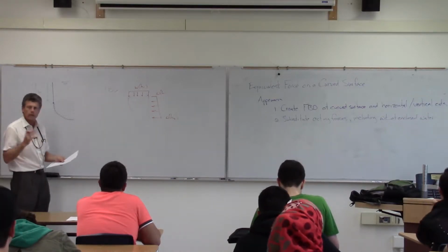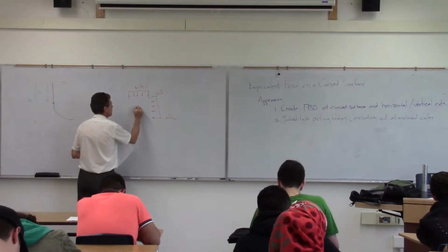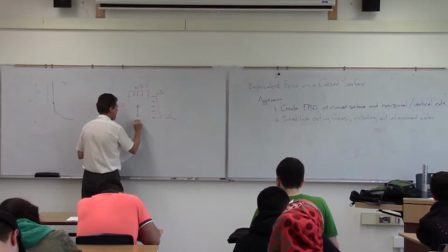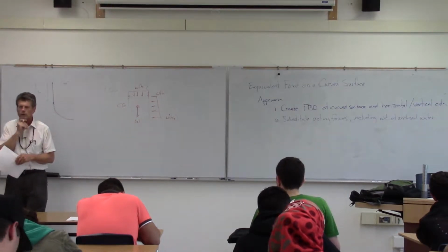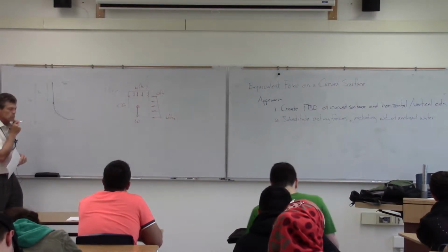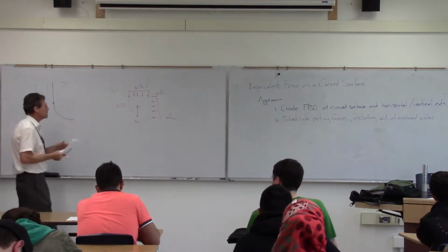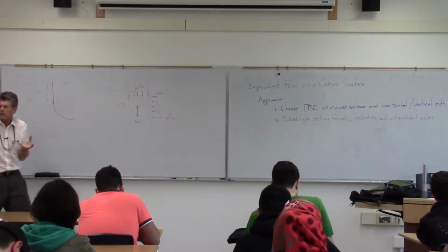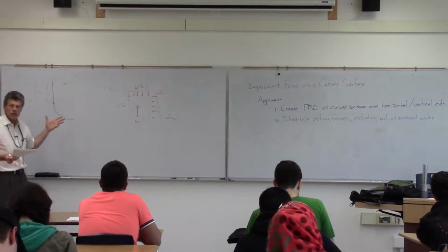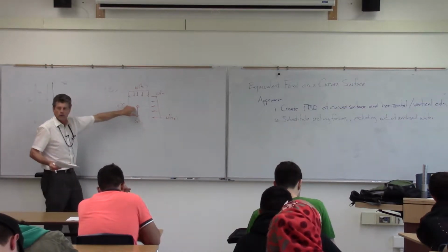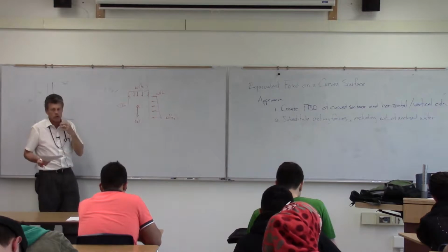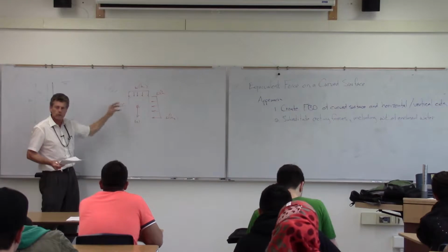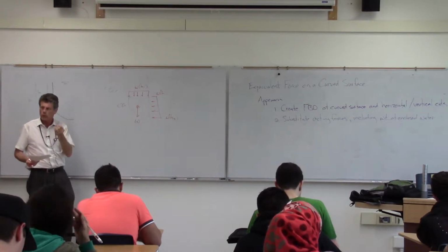The final piece then is we have to find the CG and include the weight of that enclosed volume. So that's something we can do, hopefully, if the curve is something that's nicely defined, like a parabola or a circle or something like that, we can basically just go to the back of the book, grab the CG of this area, or the centroid of this area, and since we made the assumption that it's the same material, it's water, gravity will be acting on it, so the CG and the centroid will be the same location.